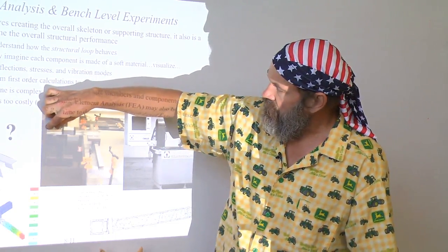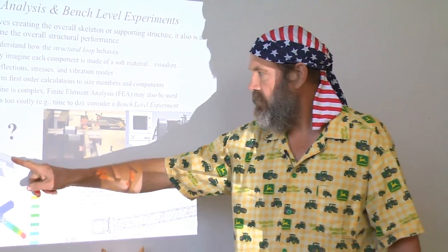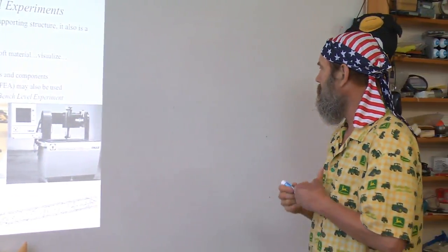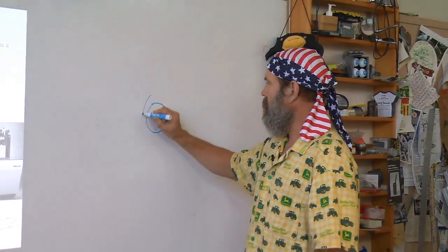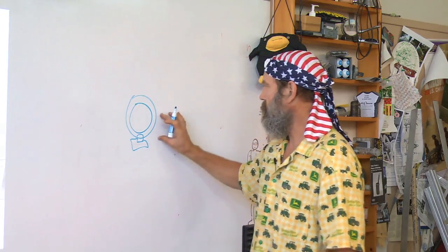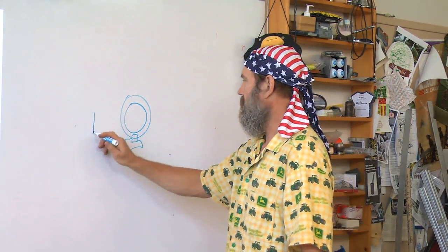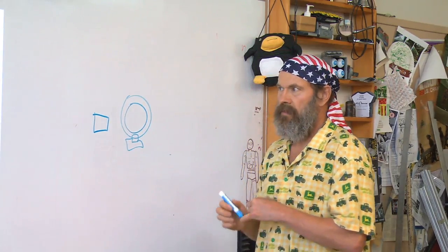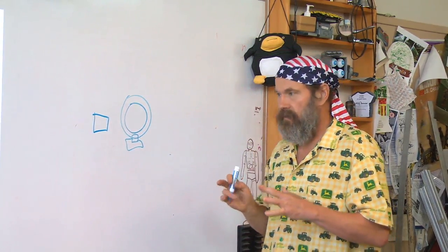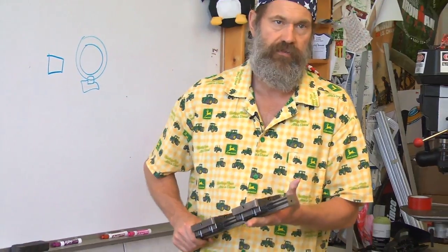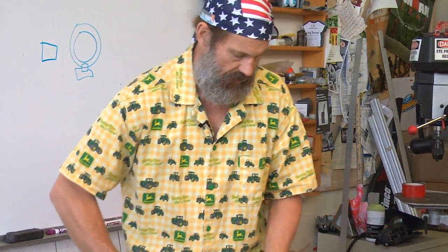The size of this steel rail, see this solid steel rail, becomes just too big. It can't compete with having an aluminum tube with a smaller steel rail and bearing. This was just much stronger in the end and lower cost than just putting a bigger and bigger steel rail. The lesson, however, was not lost that for smaller machines, you can often think about just using the rail itself as the axis.